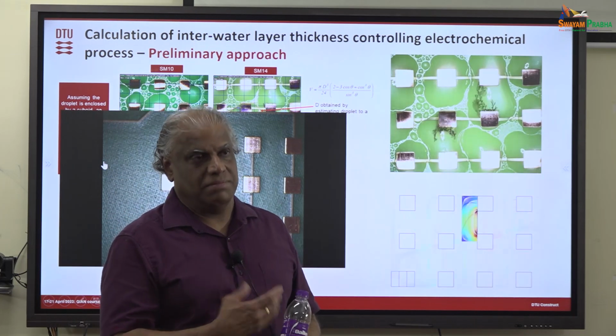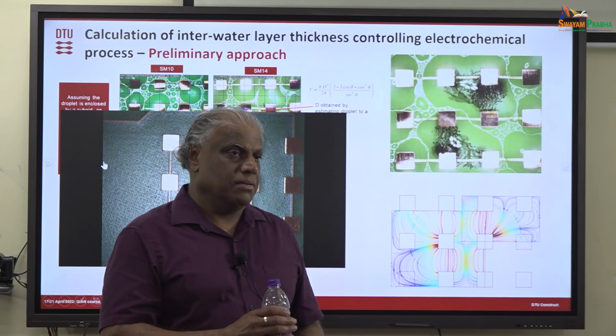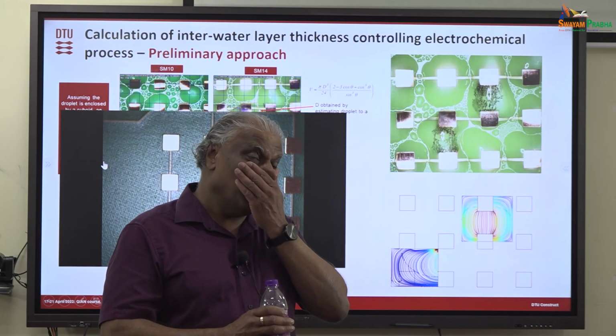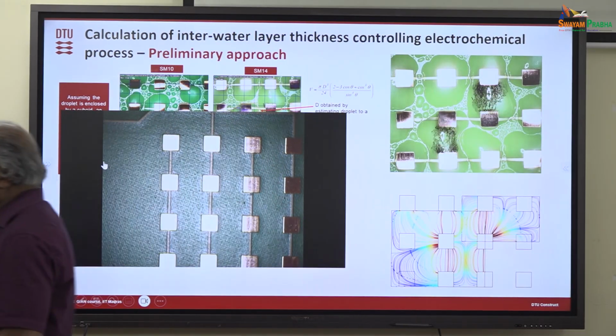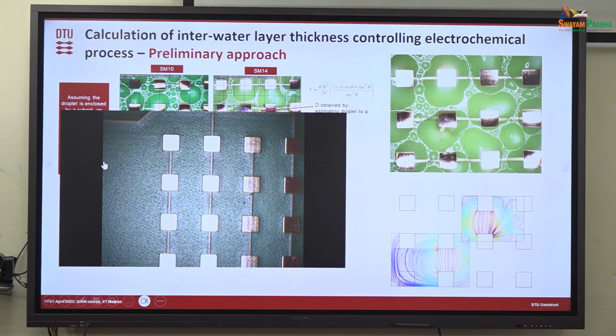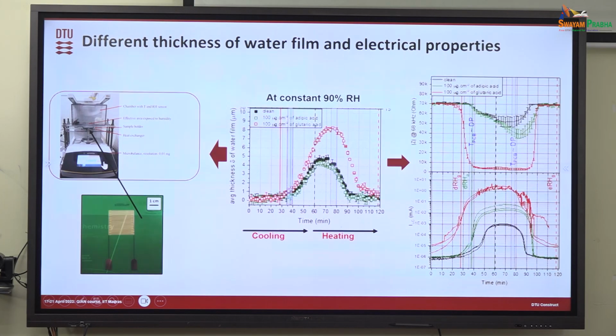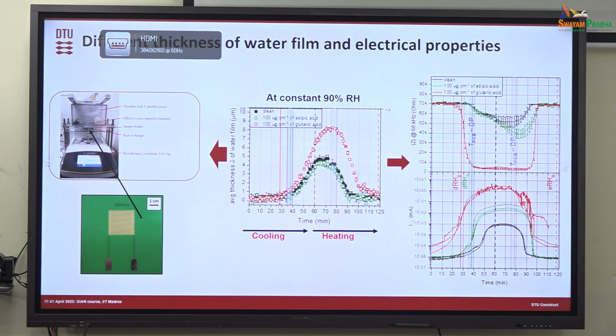That's after the experiment. This temperature we are reducing by passing some liquid nitrogen, or how? No, it is cold water. See, for example, in this case, there is a heat exchanger sitting below. That heat exchanger is connected to a coolant. Just cold water. We are producing the cold water in another system, where we can control the temperature, and we pass it through the heat exchanger.